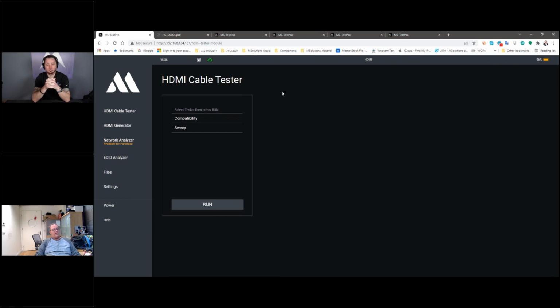Now, the moment you have high bit error rate, but still, you know, it's something in the range which is allowed, then the HDBaseT will be able to compensate on it. But the moment that it is too high and you don't know, you will see video drops on the HDBaseT, which are definitely not an HDBaseT issue.